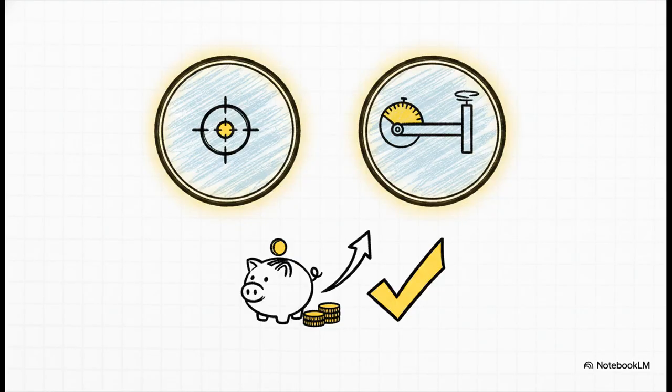So the standard now makes it very clear. Position and runout are vastly better, far more cost-effective options for defining rotating features. If you're drafting a new part today, you really should just default to position and runout. In a lot of cases, simply checking basic circularity right alongside position achieves the exact same functional goal, but without forcing your quality department into an incredibly expensive, time-consuming measurement nightmare.